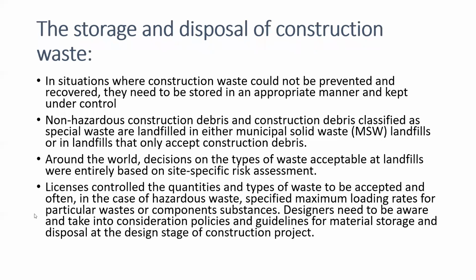In situations where construction waste could not be prevented and recovered, it needs to be stored in an appropriate manner and kept under control. Non-hazardous construction debris and construction debris classified as special waste are landfilled in either municipal solid waste landfills or in landfills that only accept construction debris.